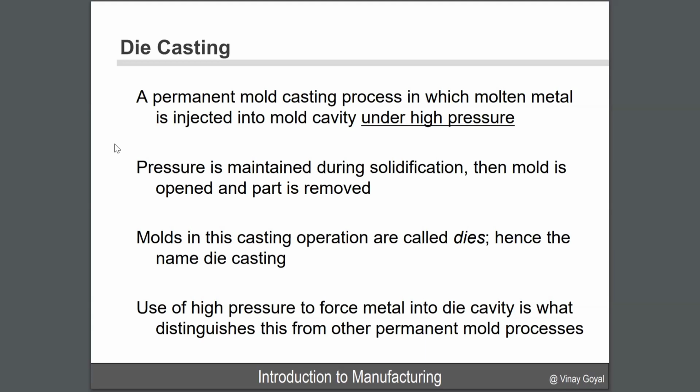That's an incomplete engineer, because that means maybe the part is not even manufacturable. You made something in the CAD software that cannot be even made, or you want to achieve a particular dimensional tolerance and you chose the wrong casting process. All those things we need to keep in mind as we work through this process.